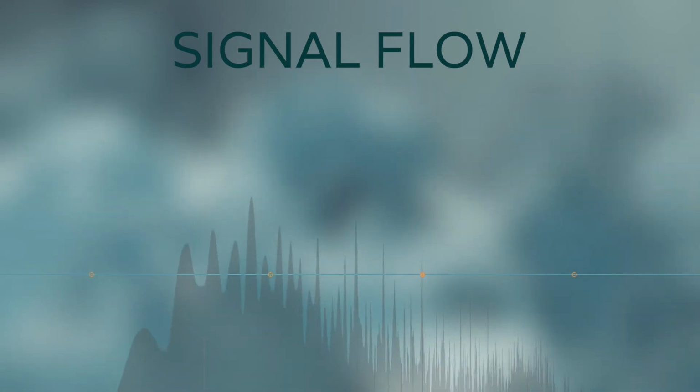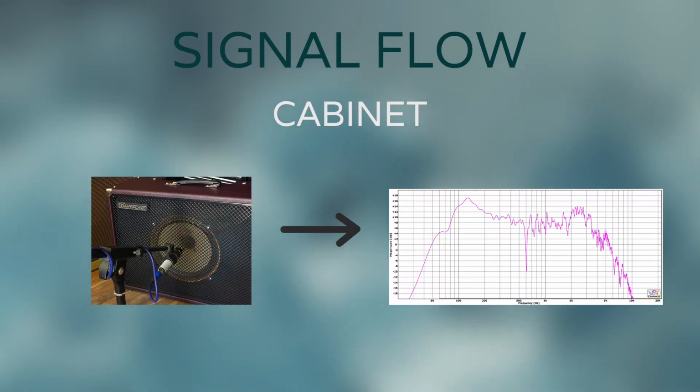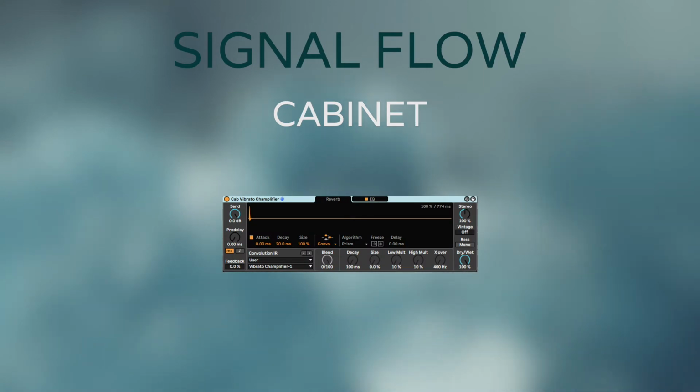The last thing that shapes the sound is a cabinet. We can emulate it by copying the resonances using EQ, compression, and expansion. A cabinet is basically a complex filter that removes some of the frequencies. In this case, we will use an IR, that is a capture of this frequency spectrum. I will put the IR used in this video, that is from my Fractal FX8. For those who want to know how to make impulse responses, I will also put the link in the description.